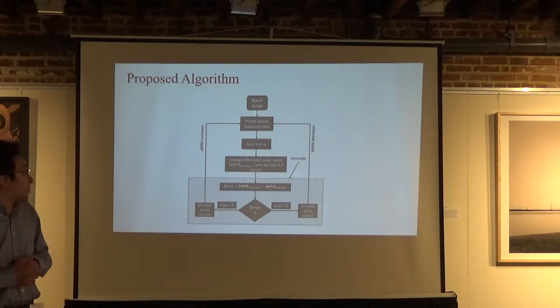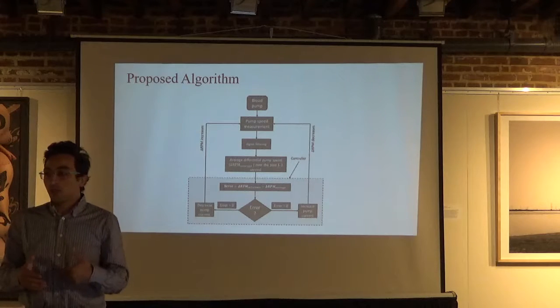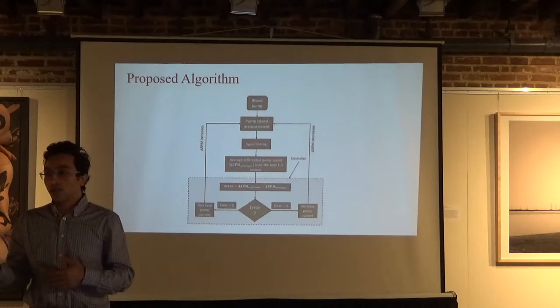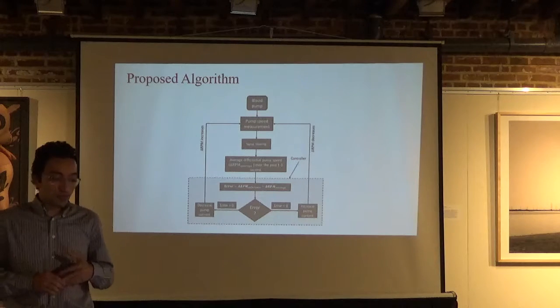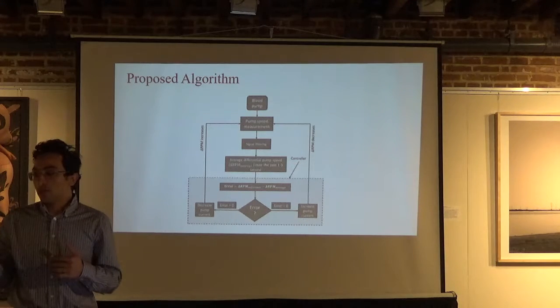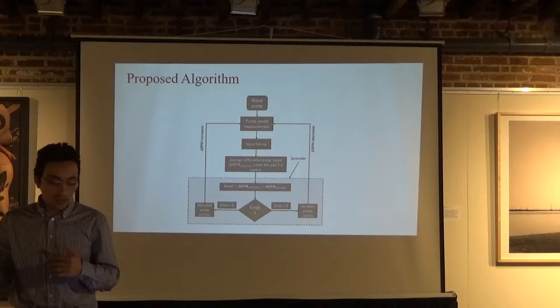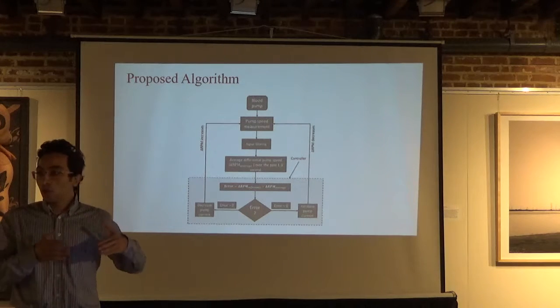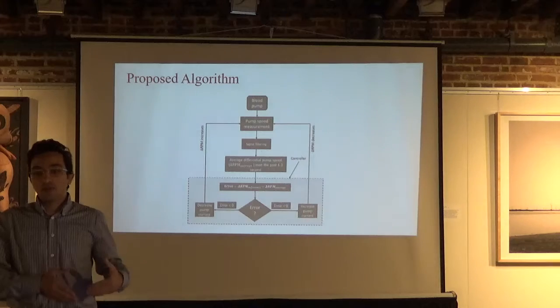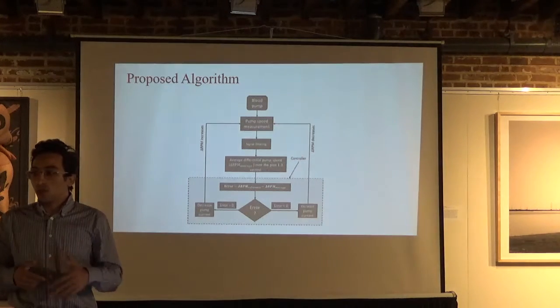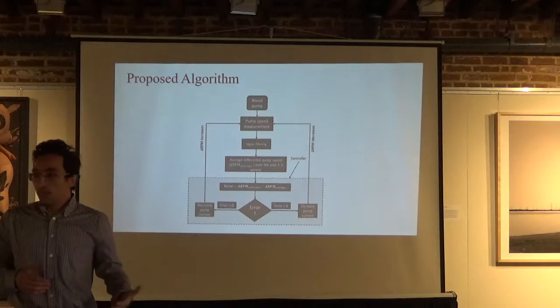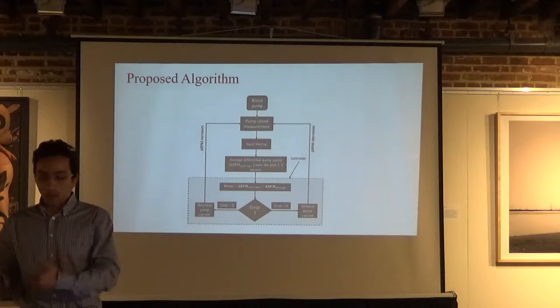So this is a schematic of the proposed algorithm, where we would measure the pump speed using phase currents or using Hall effect sensors, which do not come in contact with blood, and then obtain this signal and measure the average differential pump speed for the past 1 to 3 seconds, and then compare it to a single delta RPM reference point. If it's higher, then you need to increase the current to unload the heart more. If it's lower, well, then you need to back off and decrease the current so you don't fall into suction.